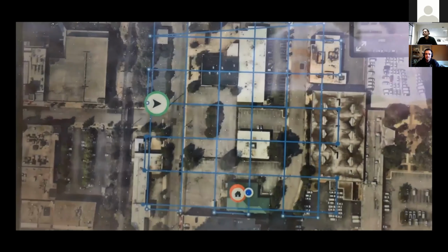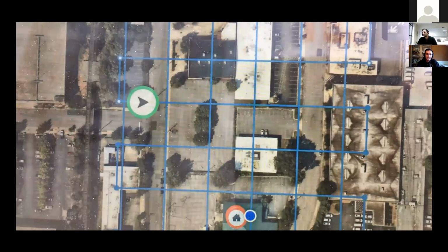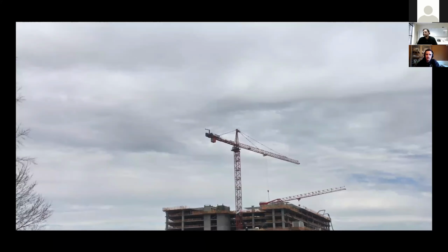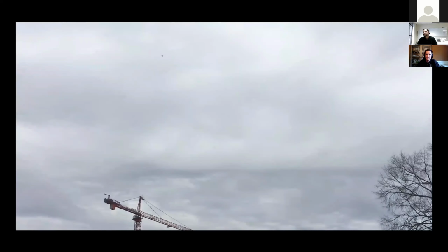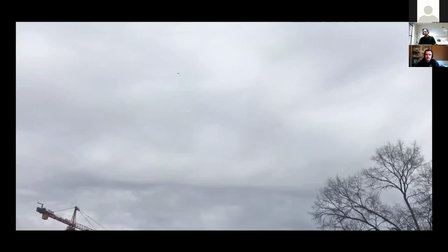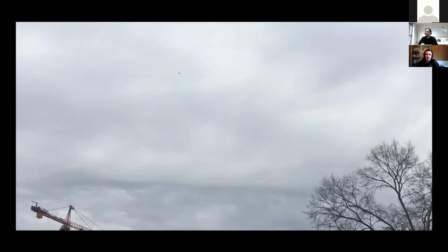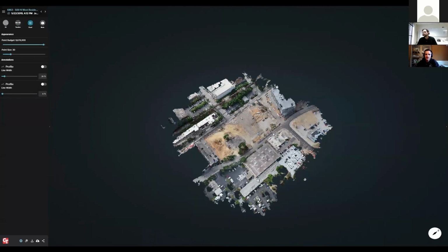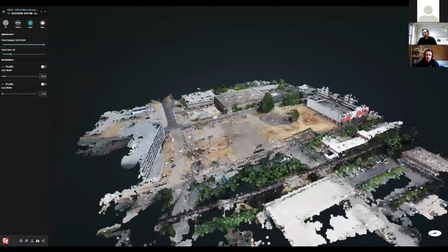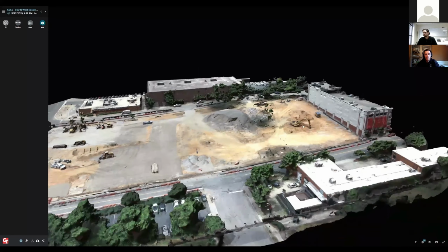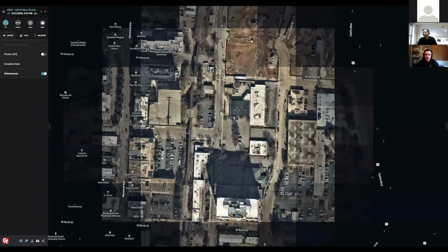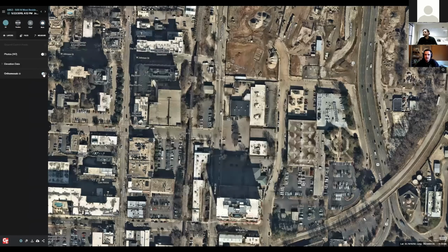And I think, Paul, that's where you're talking about the rolling shutter of the Phantom 4? I've seen the Mavic 2 coming out with a mechanical shutter. But go ahead. What I was going to say is I've seen some scans coming right out of the Mavic 2, and they look almost just as good. But that's where there may be a benefit of having the Phantom 4 in there. And I'm not sure exactly. I know there's some software, some of the stitching takes into account the different platforms, and the software will actually kind of correct that blur in a sense, knowing how much movement there is. But I think at the end of the day, a lot of folks are going to say mechanical is better. And then folks who are doing things with the global shutter, leaf shutter, they're still finding results and creating solutions.